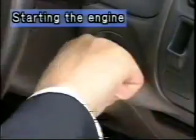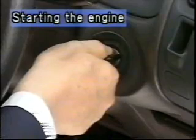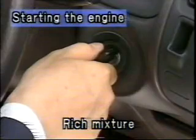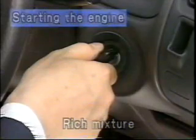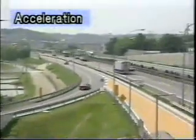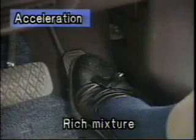Now let's look at different driving conditions, beginning from when the vehicle is started. Naturally, the engine is cold, making it harder for the fuel to be atomized. This alone is enough to create an improper air-fuel mixture. Hence, it is necessary to provide a greater ratio of fuel to air. Next, when the vehicle is accelerating, we know that fuel is heavier than air. So since the amount of air is increased when the accelerator pedal is pressed, the amount of fuel also must be increased to obtain sudden acceleration.